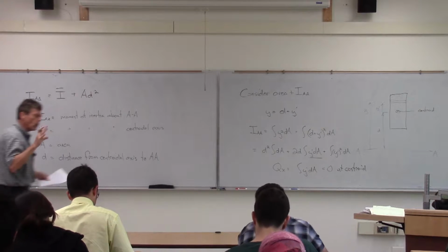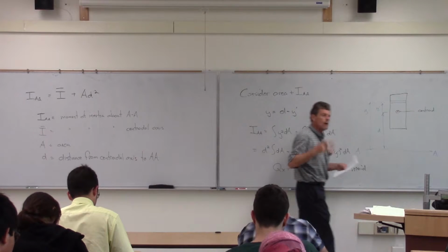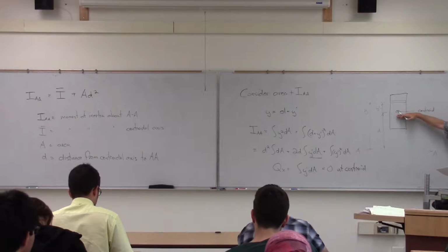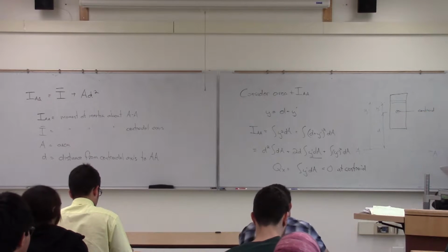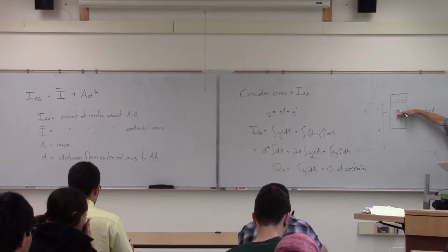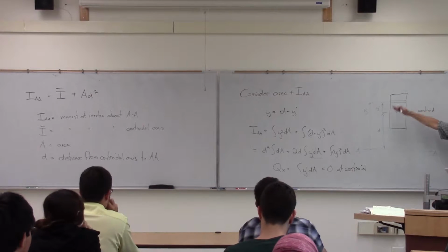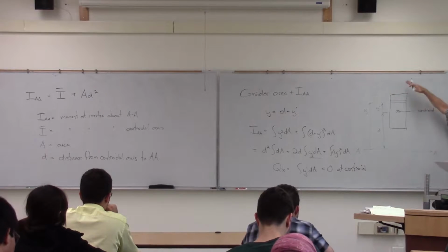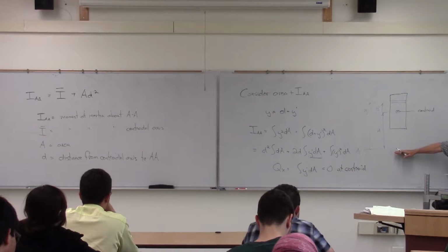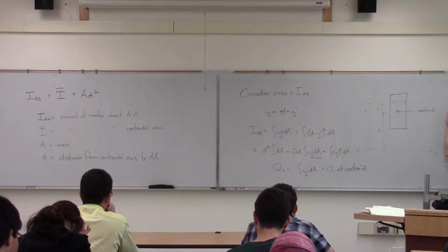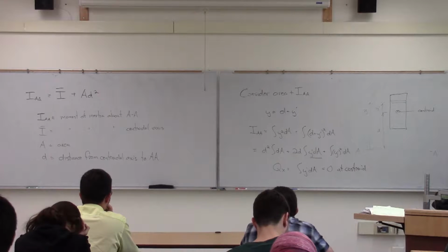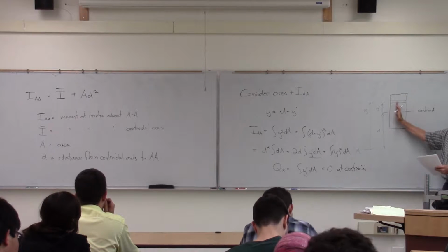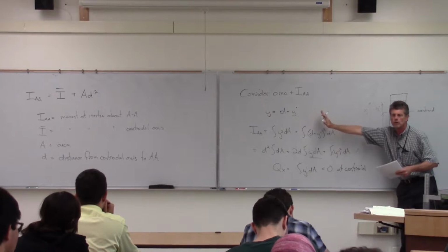Now, you'll see why the name makes sense. Parallel axis theorem basically means that I'm going to be doing a parallel axis. So I have a centroidal axis here, x or y, in this particular case x. So my parallel axis theorem says that I can find the moment of inertia about any axis that's parallel with x. So I can go down to AA, BB, whatever. Now I can't switch that vertically or go 90 degrees and that sort of thing. It's only going to work on a parallel system. But I can do the same thing for y. If I have y, then I can create moments of inertia based upon that.